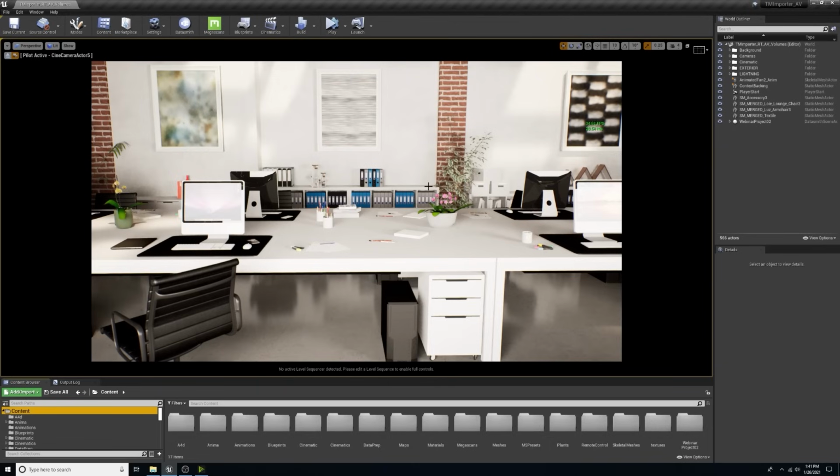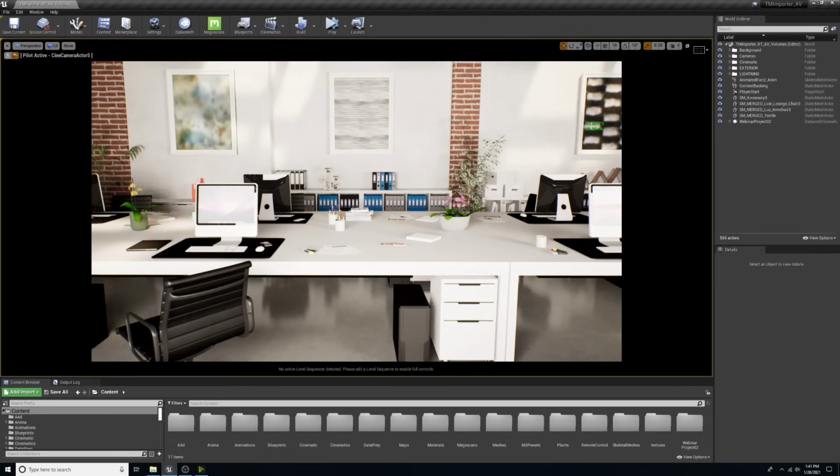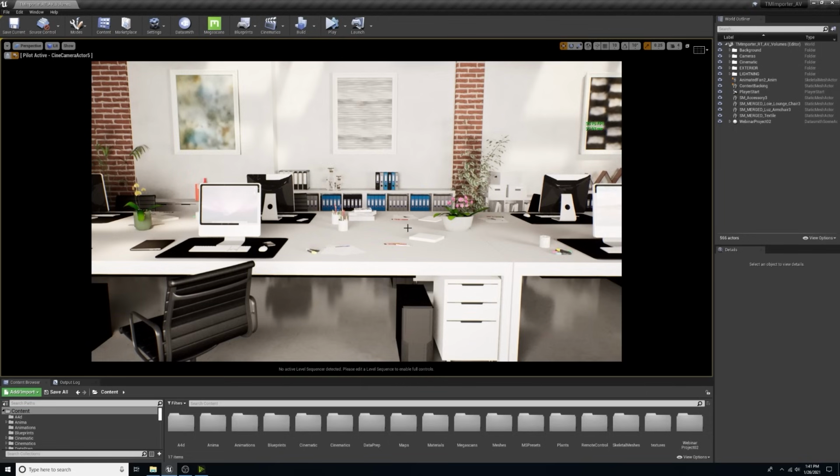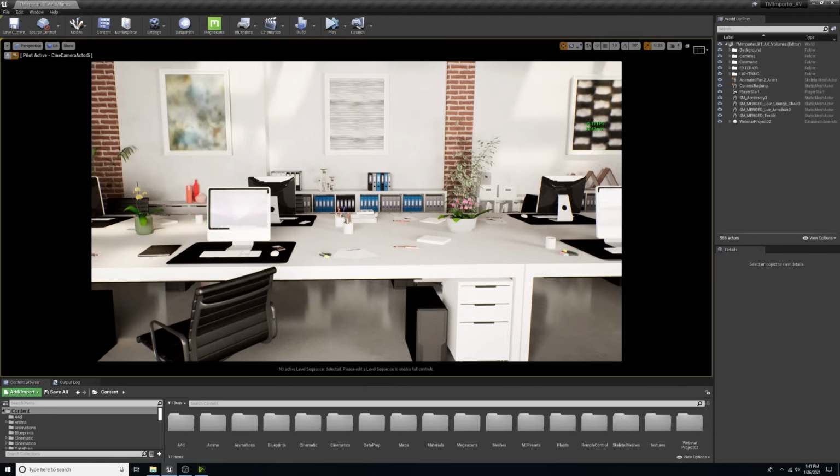Now that I've switched files, I'd like to quickly show some additional things you can do with your Twinmotion file in Unreal. If you have your own personal library of entourage that includes animated features or characters, you can import that into Unreal using FBX.